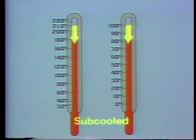At temperatures below the saturation temperature, water is often referred to as being subcooled, meaning that the water temperature is below its boiling point. In order to raise the temperature of water to the saturation temperature, heat must be added to it. We'll use this graph to illustrate the process.